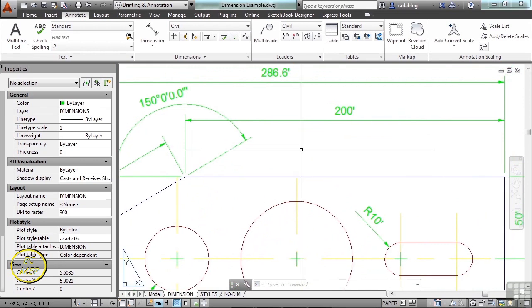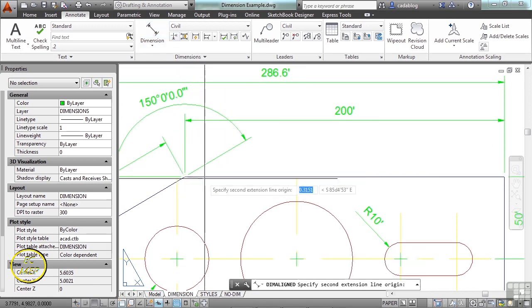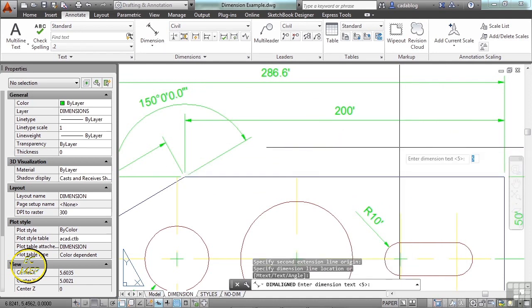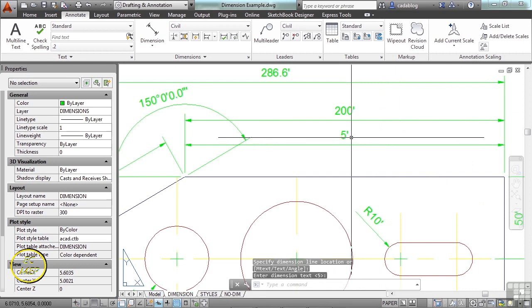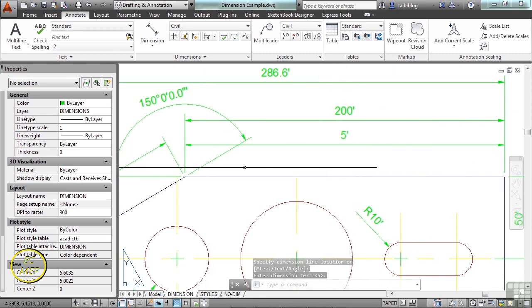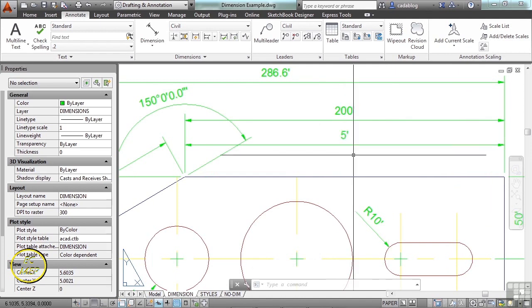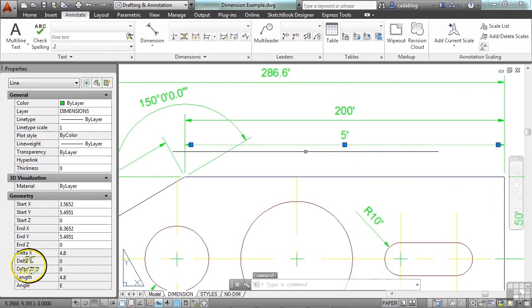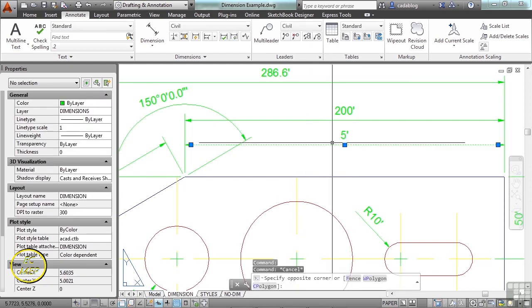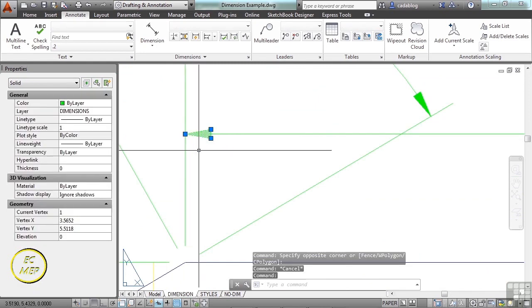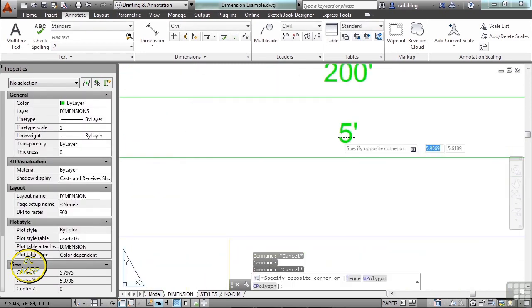If you have your Dimension Associate setting set to 0 and you create dimensions, they'll look like your style and they'll just draw everything else the way it needs to be. Except you see here, it's not scaling it properly. It's just drawing it to the scale in Paperspace. So you'll have to enter in the text the way you need it to. And it's not a dimension style. It's just a line. Several lines. The arrowhead is just a solid shape, and your text is just text.